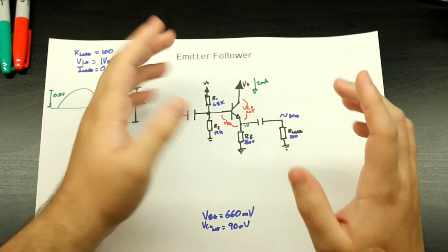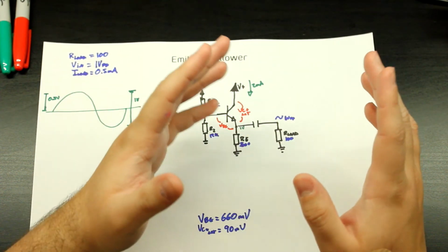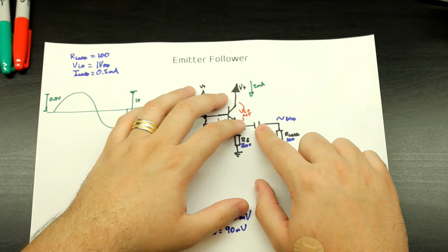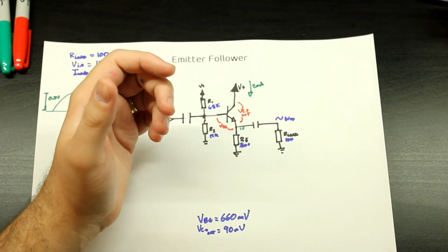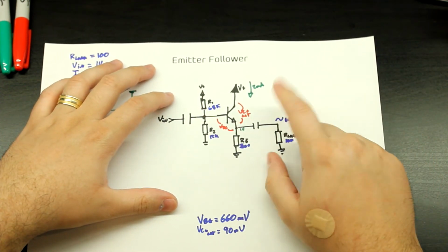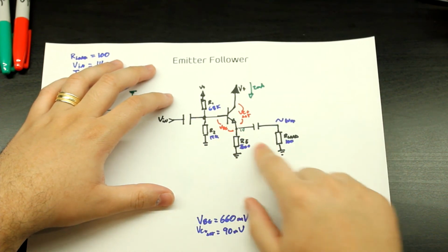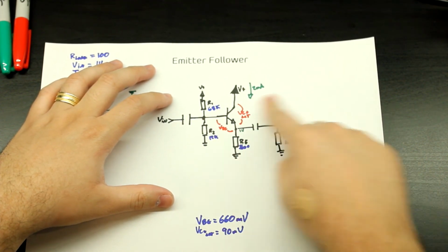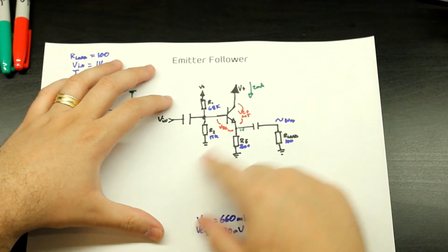But depending on what you're building, if you're building, for example, something for a tweeter or a mid-range or something like that, you can make this capacitor smaller just because you don't need that low of a frequency. To calculate this is very simple. What I recommend is you just go into, for example, LT-Spice, and you just play around with this, because LT-Spice will give you nice graphs and stuff like that.